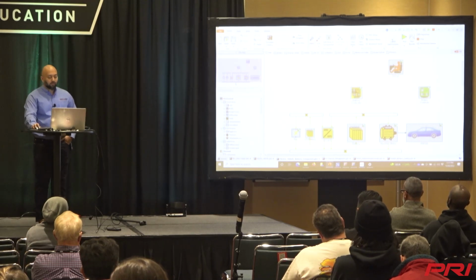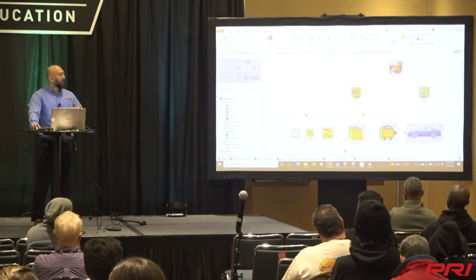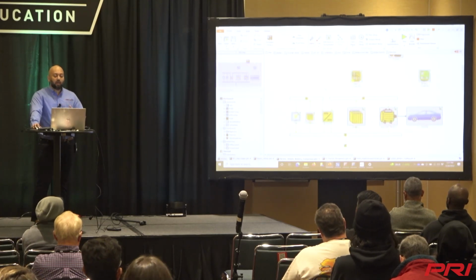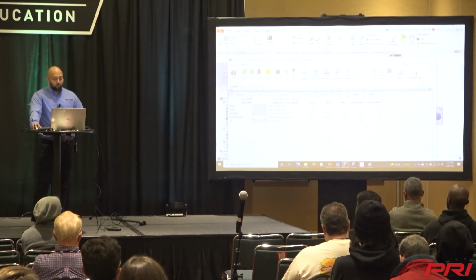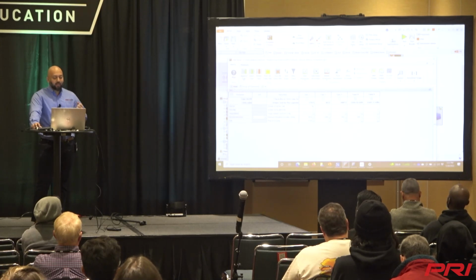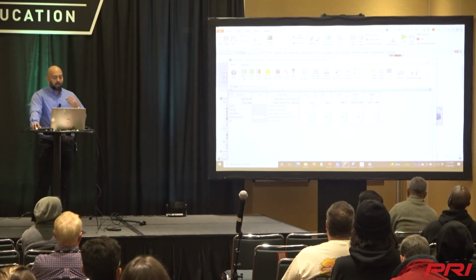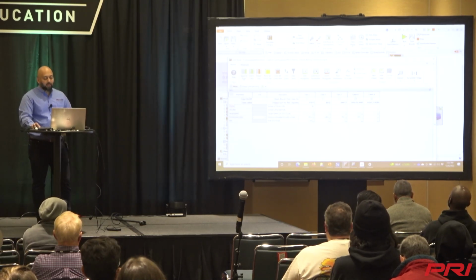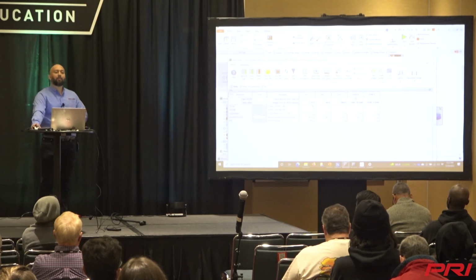So I'm going to share a model of an electric vehicle, and what I'm going to do here is show you a comparison between two battery packs. One battery pack will have 96 cells in series and three parallel branches, and the other is a 33 kilowatt hour pack, which will be 96 in series and 2 in parallel.